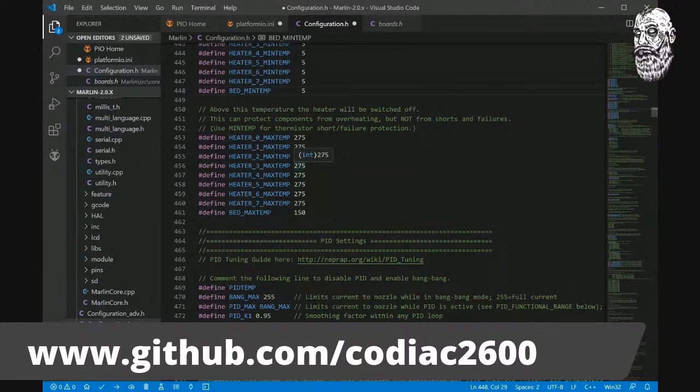Max heating temp. Now this depends on your printer. Let's say we have an Ender or a Creality printer with a Bowden setup where the Bowden tube goes all the way into the nozzle. You have a safe printing temp of no higher than really 250, 255. You can kind of do 260. If you swap it out for Capricorn tubing, you can get up to a little bit higher. The marketing hype on Capricorn is a little bit suspect because it's still off gassing.